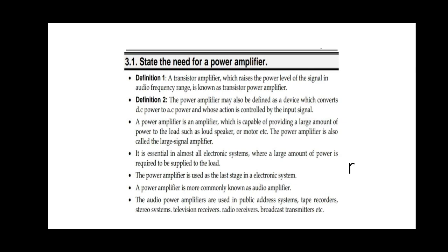Types of amplifier: voltage series is called voltage amplifier, voltage shunt is called transresistance amplifier, current series is called transconductance amplifier, and current shunt is called current amplifier. So amplifier bandwidth increases in all the cases. The bandwidth is increasing, and distortion is decreasing, in all the types of negative feedback.